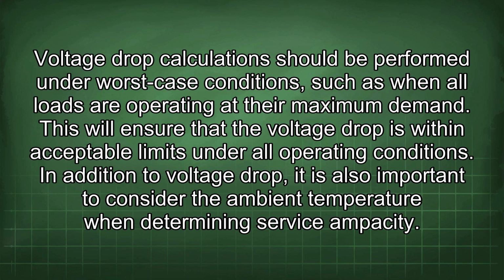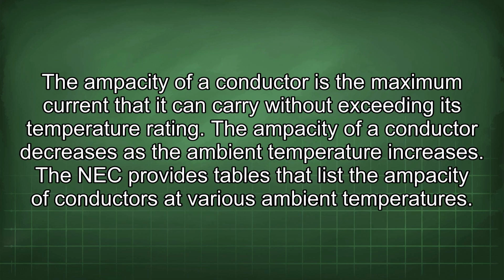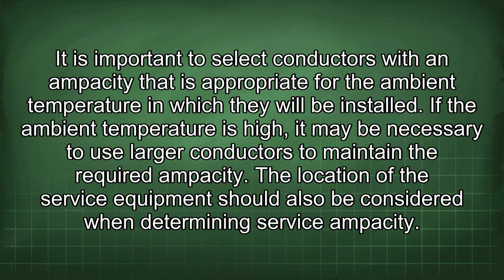In addition to voltage drop, it is also important to consider the ambient temperature when determining service ampacity. The ampacity of a conductor is the maximum current that it can carry without exceeding its temperature rating. The ampacity of a conductor decreases as the ambient temperature increases. The NEC provides tables that list the ampacity of conductors at various ambient temperatures. It is important to select conductors with an ampacity that is appropriate for the ambient temperature in which they will be installed. If the ambient temperature is high, it may be necessary to use larger conductors to maintain the required